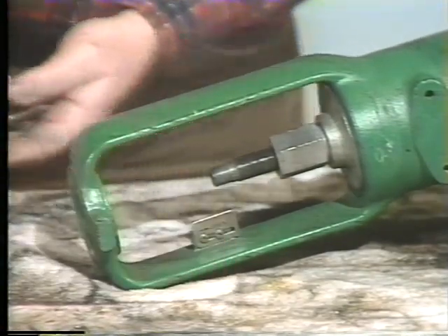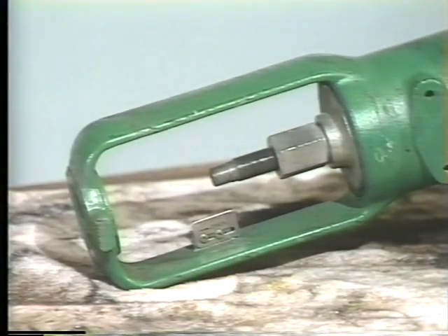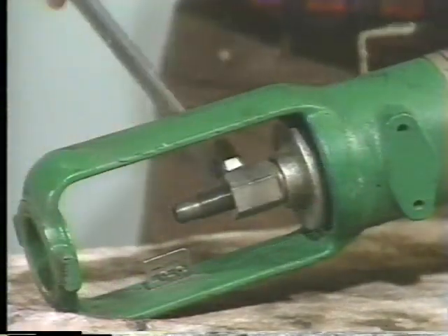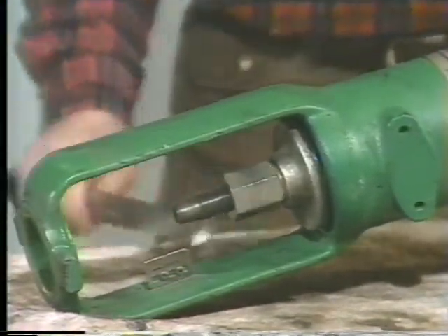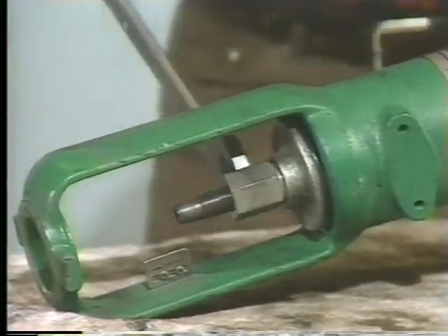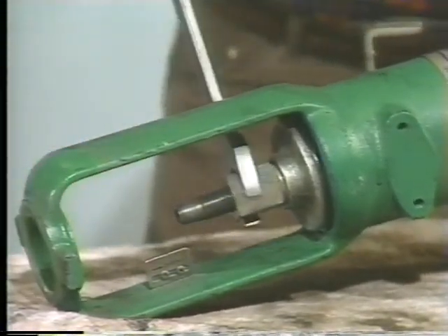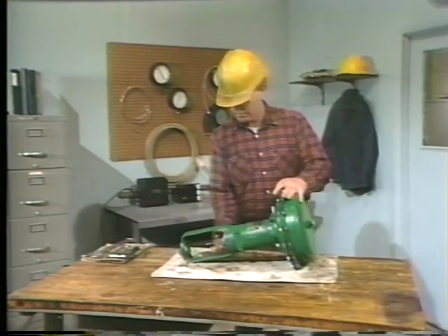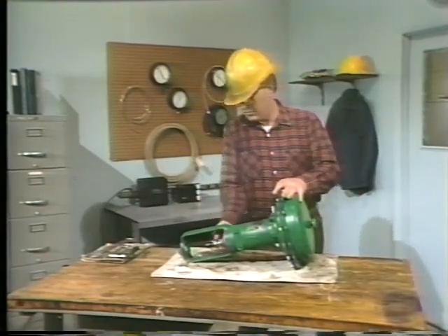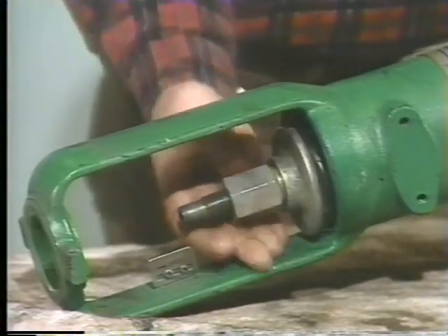Above the stem connector and threaded onto the actuator stem is this spring adjustment nut. This nut can be tightened or loosened to adjust the tension of a spring, which we'll be able to see as soon as the technician removes the nut. It's important in disassembling a diaphragm actuator like this one that the first step is to relieve the tension from the spring by loosening the spring adjustment nut, making it safe to disassemble the rest of the actuator.